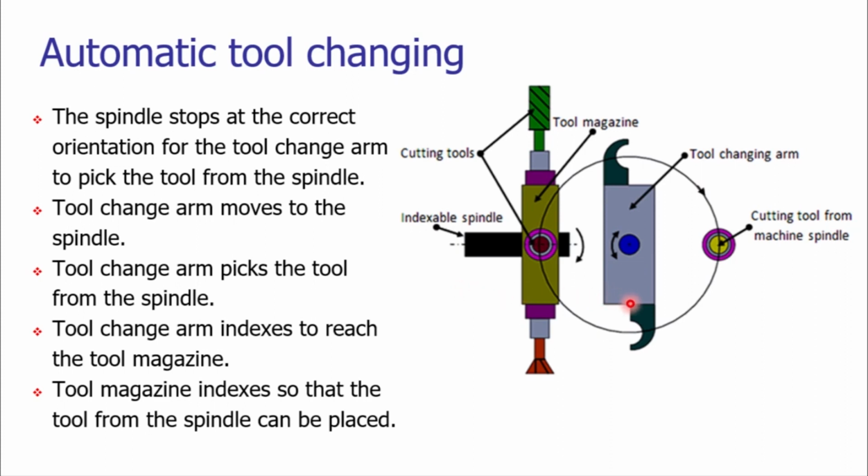Then the next 90 degrees would be operated. As we are operating the next 90 degrees, the tool will be put at the desired location and simultaneously there would be mounting of the next tool. So in this way we can have the efficient tool changing operation carried out.